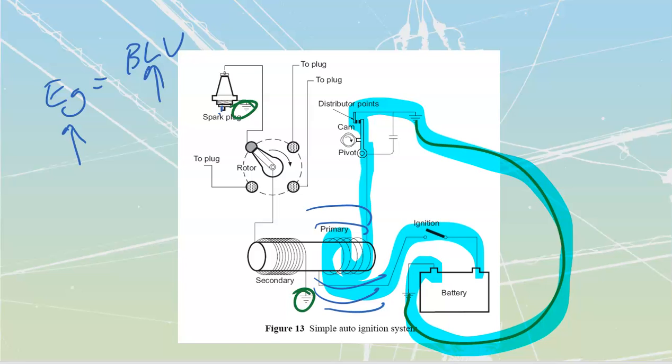If you've done any sort of residential wiring where you're pulling in the low voltage, the Ethernet, the data, the tel, all that stuff, you know that you've got to keep that separated from your line values of voltage. The higher the value of voltage, or the more critical the low voltage system is going to be, the further away you have to keep that separated so that you don't end up with interference.